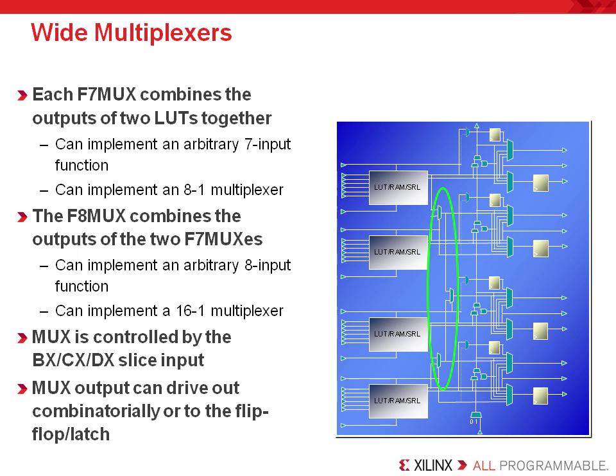Be aware that if you're going to code for a large multiplexer, you must code with a case statement in your HDL. This is required if you expect your synthesis tool to infer this mux structure.